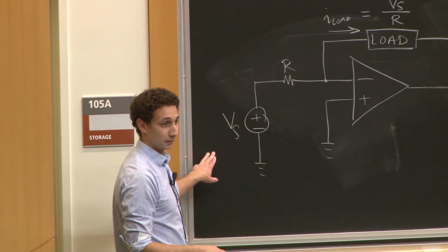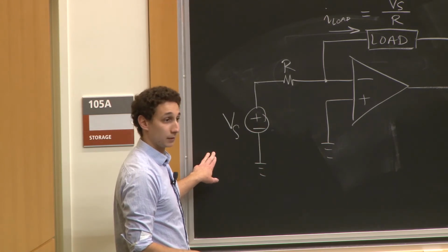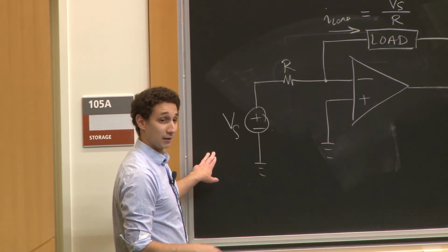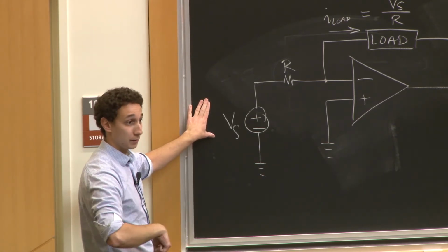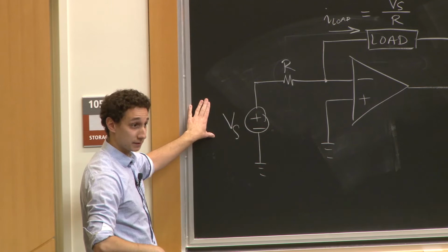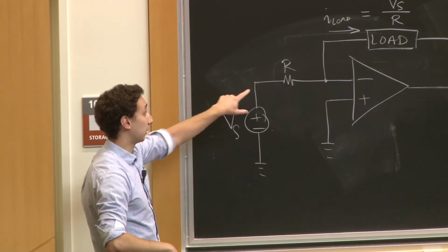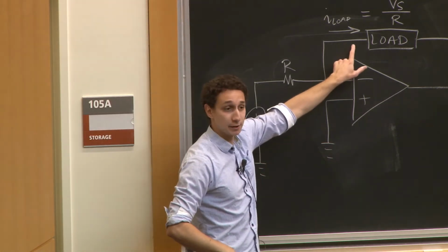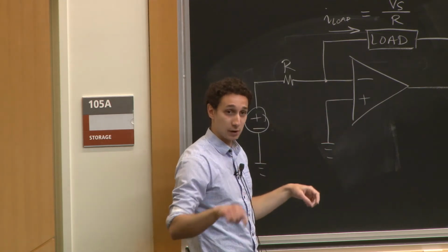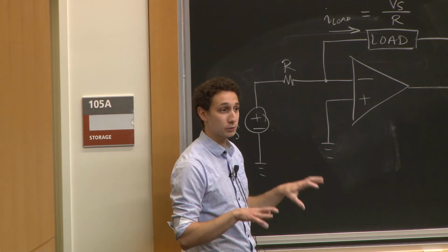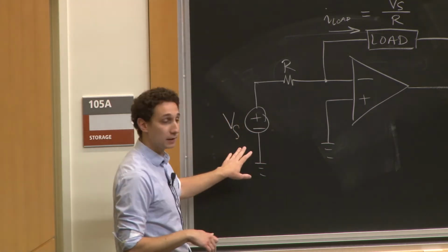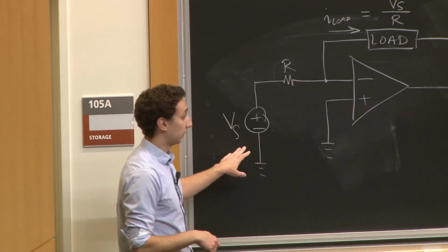Yeah. Well, now we can have two voltage sources that have opposite signs and just switch, not really switch, now it's just turning them on and off. Yes. To get the current to reverse. So now what we can do is we can take a voltage source that switches between plus some voltage and minus some voltage, and we can plug that into our circuit, have a capacitor here, and that will give us that triangular wave. So we'll switch between a positive current and a negative current. We don't need those two current sources anymore. All we need is this one voltage source, okay?